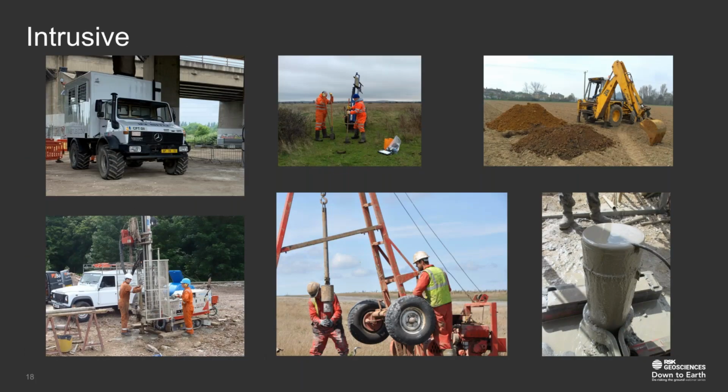Right, intrusive techniques. There are many intrusive techniques to consider, and they all have their own limitations. You could do trial pits and trenches, so like in the top right of the slide. These are undertaken with hand tools or could be using a machine excavator to visually inspect the soil layers and collect samples. They're very useful for shallow investigations. It's worth bearing in mind that generally you can only get disturbed samples from this type of technique unless you're going to start including shoring and getting man entry permits.